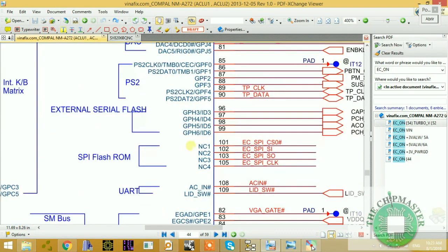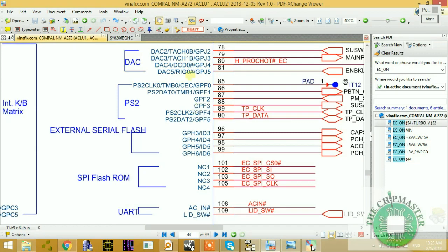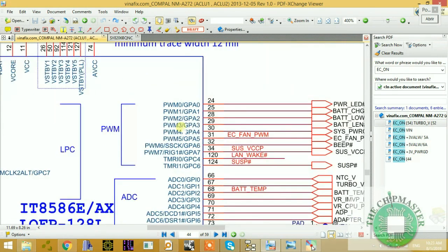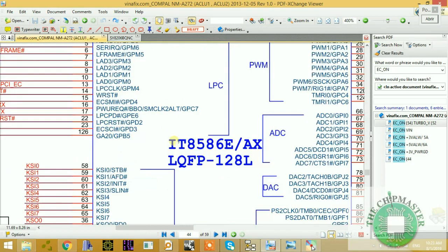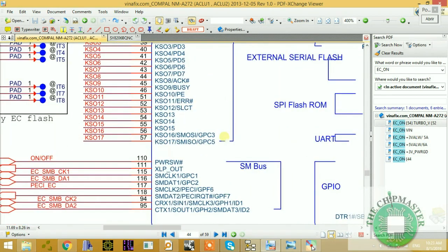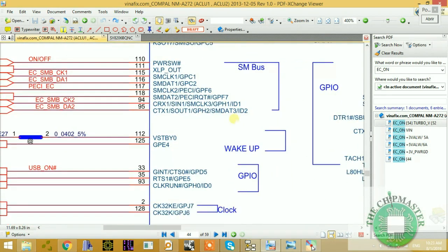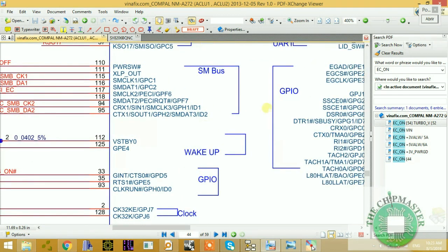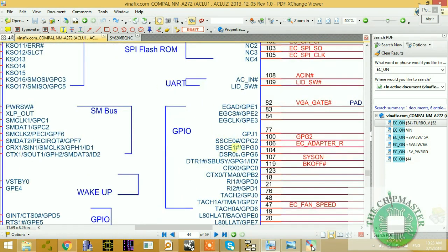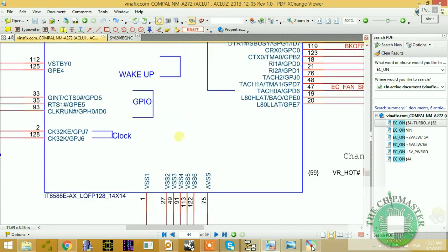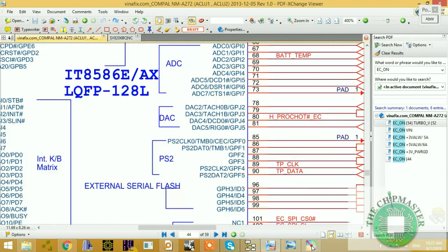They all have GPIO input output pins, and they will be configured to do specific functions, right? So this indicates that the I/O controller successfully initialized reading with the working conditions. So the supply is okay, the reset and the GPIO section will be supply, reset and clock. Adapter detection, it will configure its GPIO pins and do its specific functions, as you can see, right?